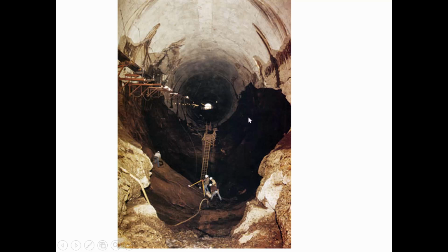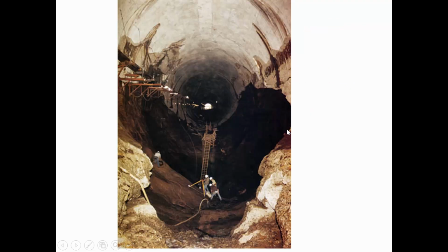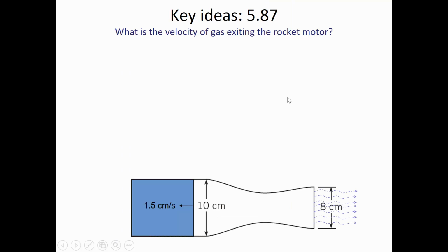And eventually it threatened the dam, so that spillway, you can see that the location of it is in close proximity to the dam, so if it starts to scour and actually gets into the dam structure, then the whole thing could fail.